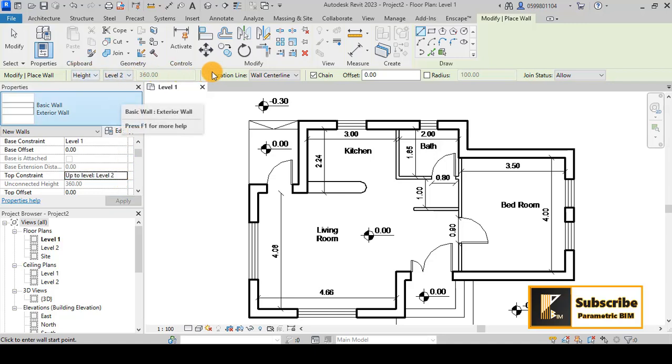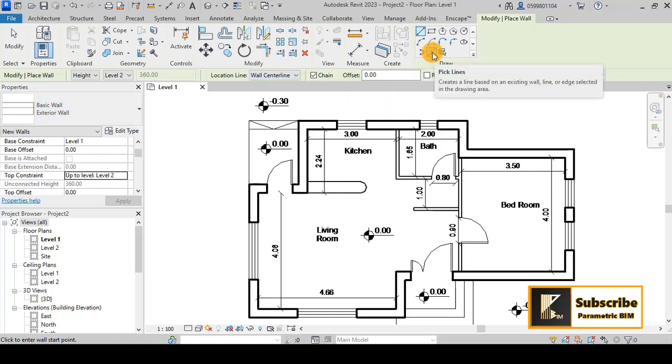Also, as you see, I have a green tab here. You can control the drawing from here. For example, the location line, which is the wall center line, core center line, or exterior and interior. You have the opportunity to choose from these. We will talk about that in a separate video about walls, but for now I will draw from the wall center line, and I have the opportunity to pick lines. I have these lines from AutoCAD, so I will pick these lines to draw over them.